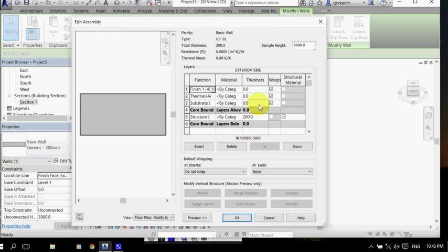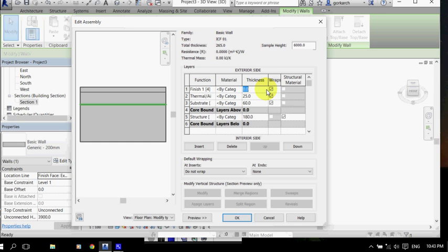Let's go from structure. So for, let's say, typical ICF 300 thick, I will need probably 180 millimeters of concrete inside of my ICF form. Substrate, that's my styrofoam. I'll use, let's say, 60 millimeters of rigid insulation. Thermal air, 1 inch, so let's say 25 millimeters. And brick veneer, let's make it 90 millimeters for brick veneer.